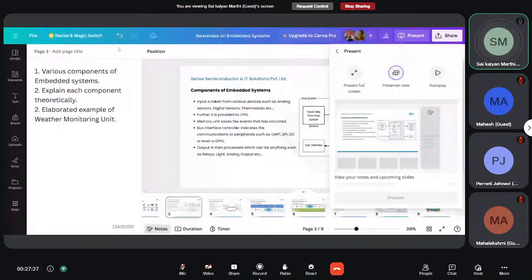So the hardware team needs to decide what kind of product or sensor we need to integrate in our system, what the interaction of the controller and the sensor is, and what the communication protocol between them is. That needs to be analyzed, and they need to provide some kind of design. This hardware design is nothing but a block diagram view of everything, and it includes schematic, PCB designing and layouts.